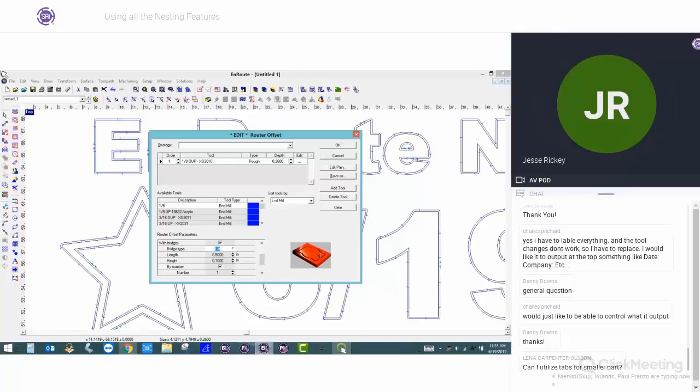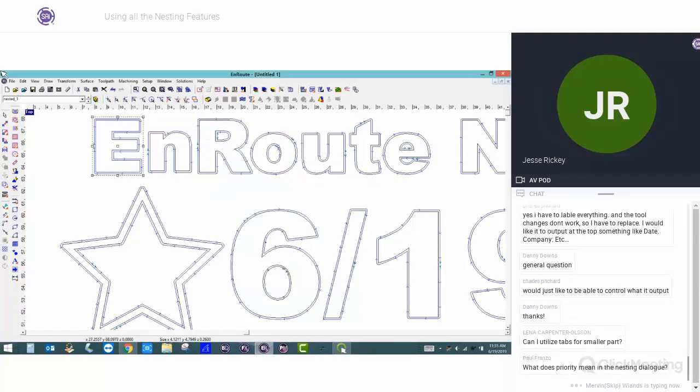So inside here, just remember that everything's based off the bottom of the toolpath. So right now I have 0.26, which would be for 1/4 inch material. So I actually need to make the height of this tab 0.01 bigger than I would normally, because I'm going a little bit deeper than the actual material itself. And that's something that we're going to cover in one of our future webinars, is tabs and onion skinning.